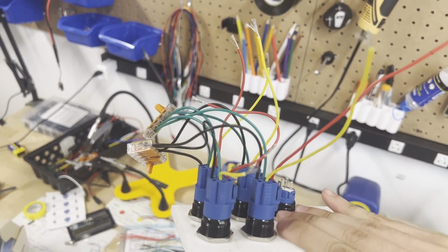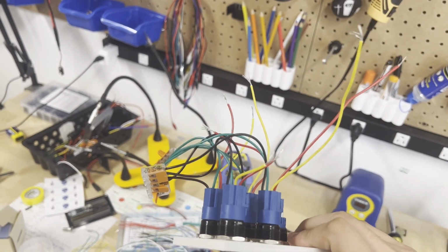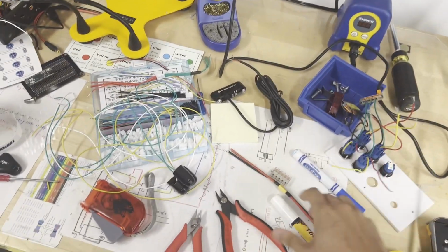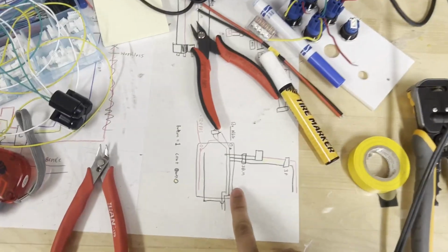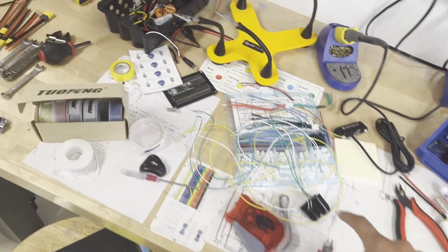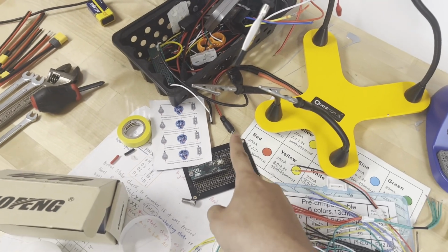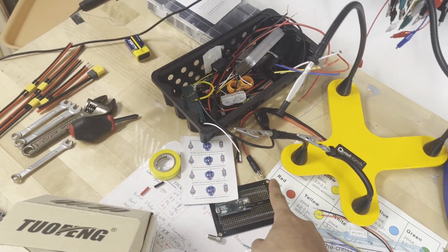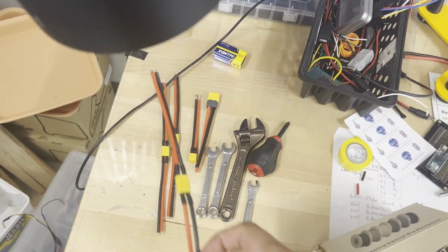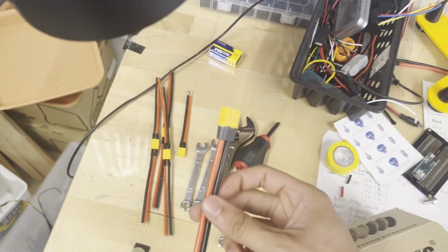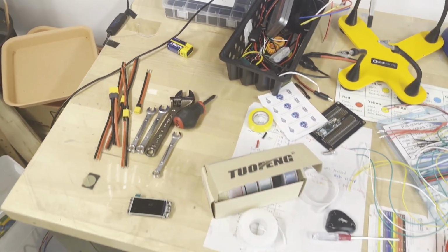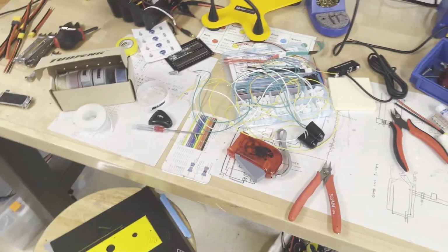I also handled the wiring totally differently in my first couple of attempts. Check out my previous videos to see that chaos. But, you know, I did a circuit board that definitely did not work. I practiced using barrel connectors, which burned out on me because I was pulling too many amps. So now I'm moving on to using XT30 connectors, and then for my horn, which pulls more amps, I might use an XT60. Not really too sure yet, but that's something that is just gonna have to come with time.